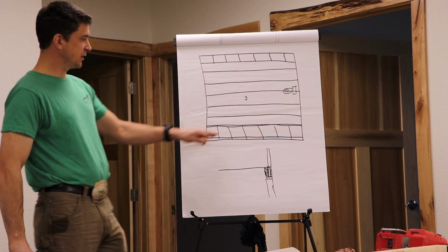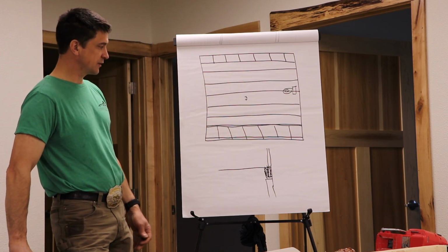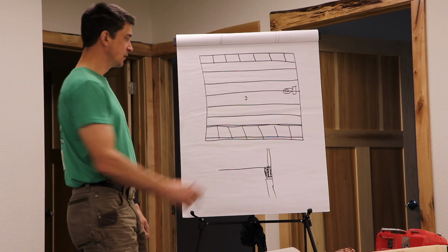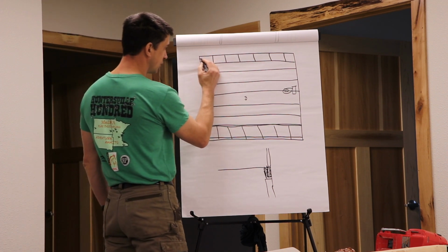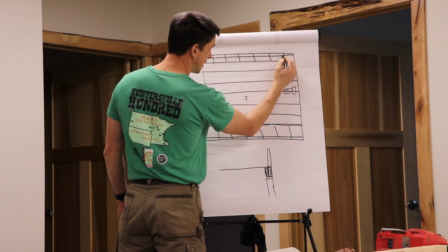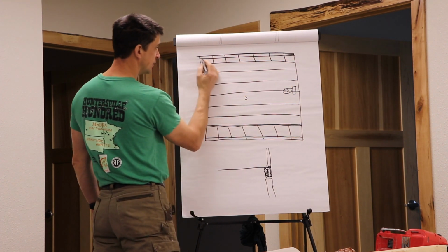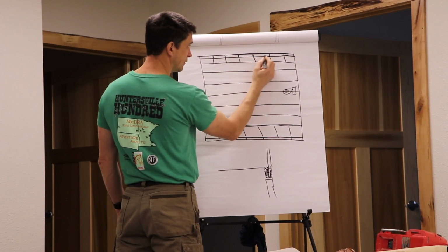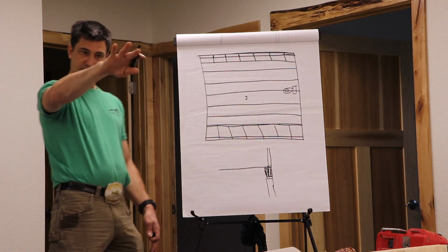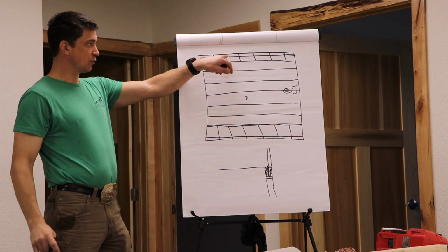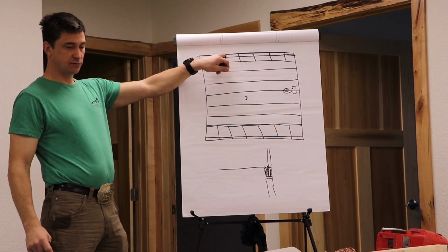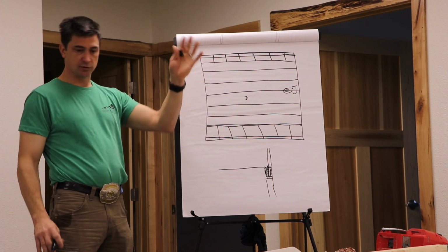The benefit of doing your end joist framing like this, one, it gives you support, so when you put your bottom plate for your wall on here, you've got support under that wall so that it can't tilt in or make this rim joist here tip out or anything like that.